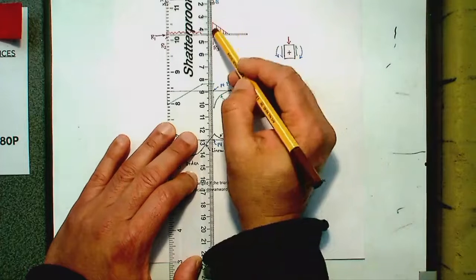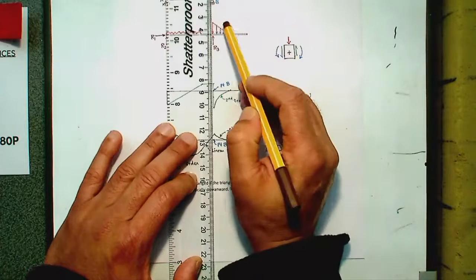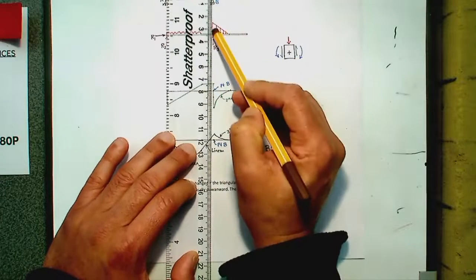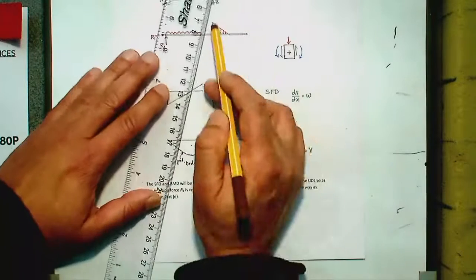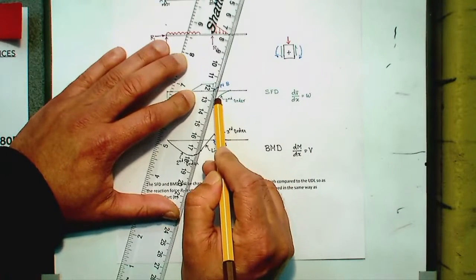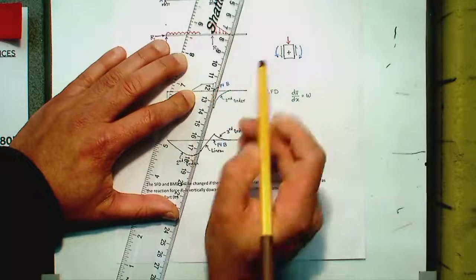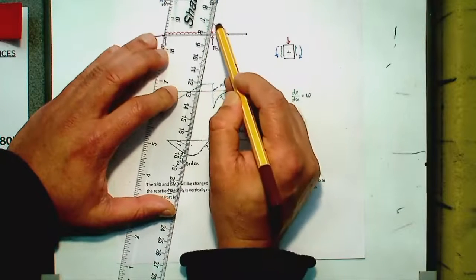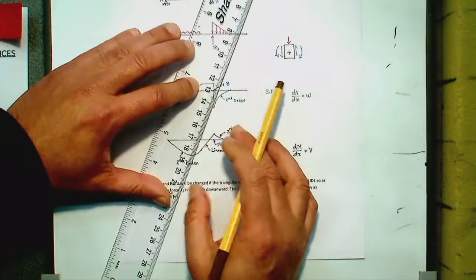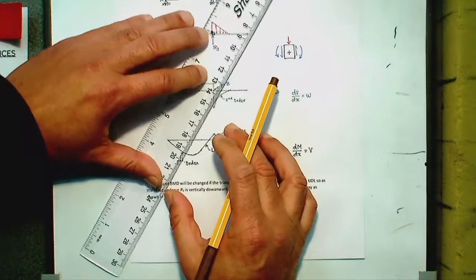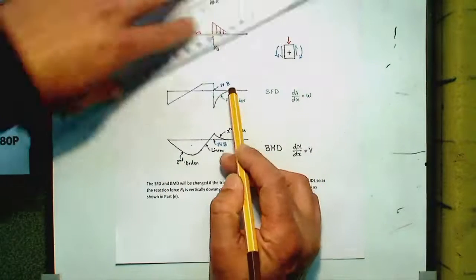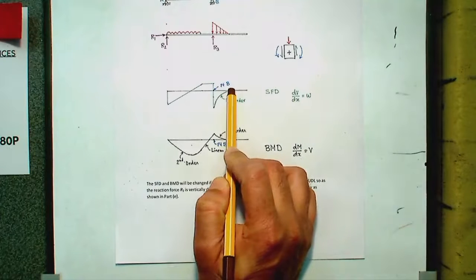And then you have got a load coming down, but this load decreases in intensity. So very high intensity at the start, and it's a positive load. So I'll start with a very high slope, a positive slope, and then load intensity decreases and becomes 0 at this point. So my shear force diagram would have a slope which will be positive and start to decrease, and ultimately it will be 0 at this point.